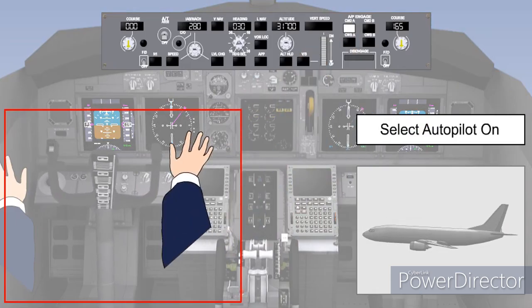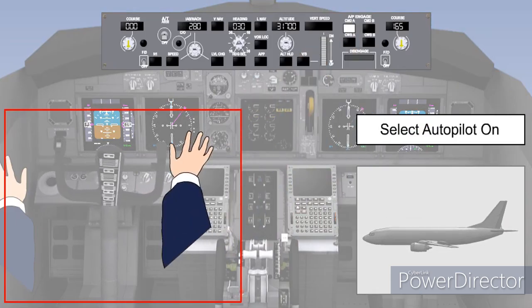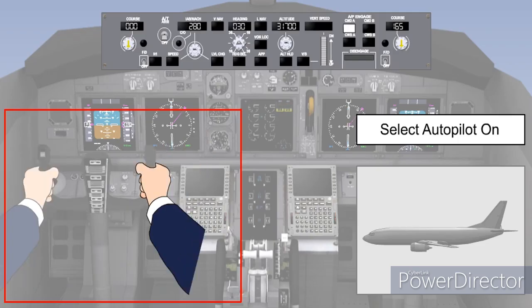When the autopilot is engaged, it has to be capable of continually trimming the aircraft in pitch to account for variations of the centre of gravity, configuration and speed. If this did not happen, out of trim forces would be felt on the servo motor, and at the point of autopilot disengagement, a pitch input would occur, causing the control column to be snatched or jerked. To allow for this, an automatic trim or auto-trim system is fitted to continually remove any out-of-trim forces in pitch when the autopilot is engaged.